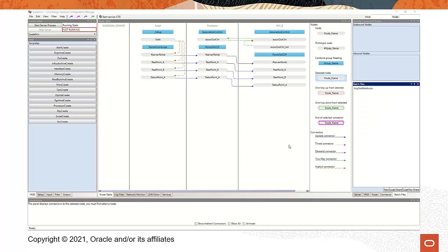We'll need to adjust the server parameters for the simulated SCADA configuration. Like I mentioned earlier in this tutorial, the LEC server needs to have 2 ports specified at startup to run successfully. Remember, most customers will not need to adjust these ports because they will only run one LEC server instance on one computer. For the purposes of this tutorial, we will change the ports used by the instance simulating the SCADA server configuration because 2 instances can't use the same port on the same computer at the same time.